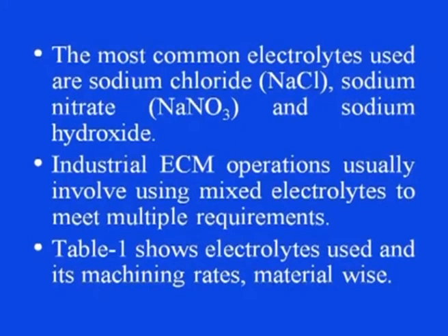The most common electrolytes used in the ECM process are sodium chloride, that is common salt solution, then sodium nitrate and sodium hydroxide. Industrial ECM operations usually involve using mixed electrolytes to meet multiple requirements. The next table shows the electrolytes used and their machining rates as far as the different materials are concerned.